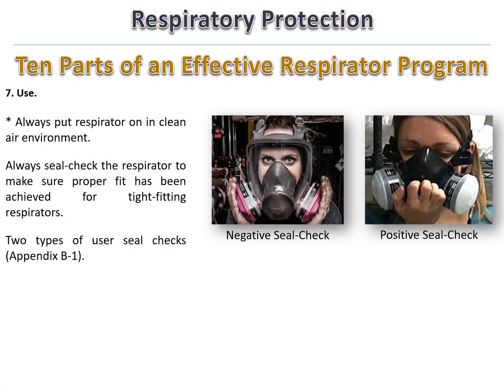7. Use. Always put the respirator on in a clean air environment. Always seal check the respirator to make sure proper fit has been achieved for tight-fitting respirators. Two types of user seal checks, Appendix B-1: negative seal check and positive seal check.